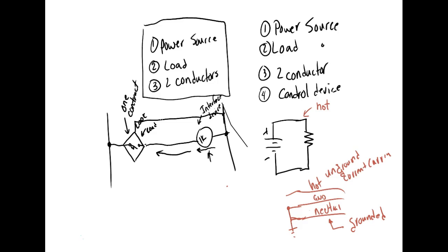Now, on these solid state sensors, especially if we have what we call a 3-wire sensor or a 4-wire sensor, anybody know the difference? With 3-wire sensors, two of them are required for power, and then one is required for the load, right? Okay, so what would a 4-wire sensor be? This is the problem we have. The temperature sensor that we have is a 4-wire sensor.